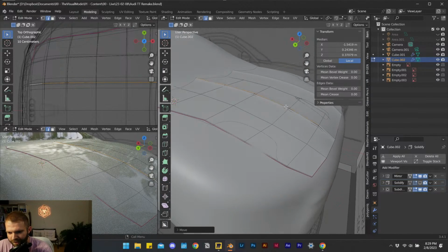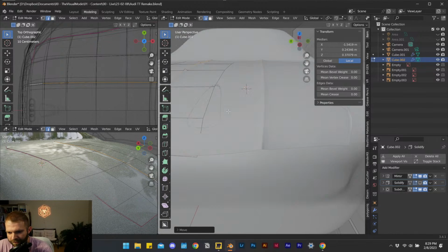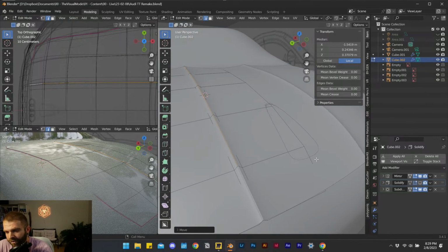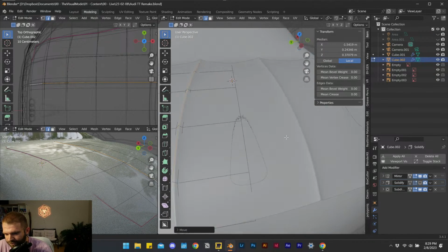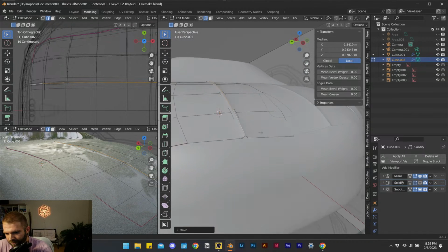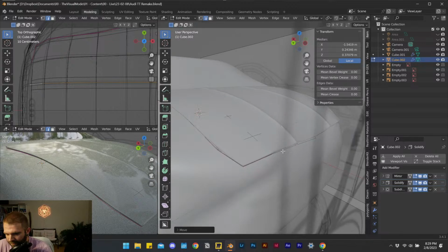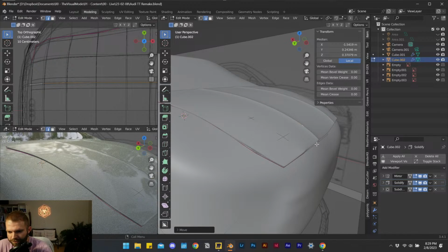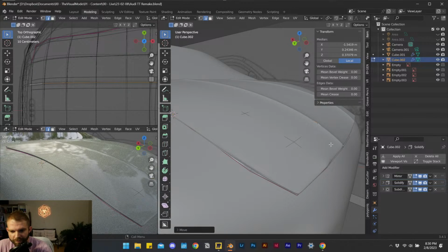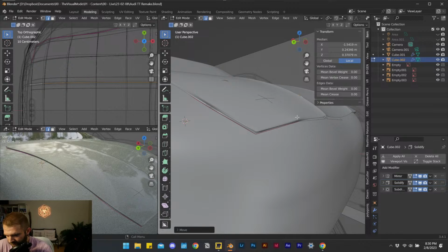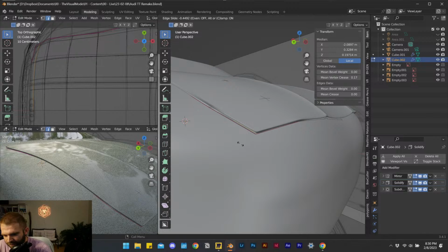And we see since we have our modifier, the mirror modifier, we're getting it over on the other side as well. So we'll turn on solidify, and see how our job here is looking. So not bad at all. What I am noticing is there's some weirdness happening at this edge, so it'd probably be worth adding a loop cut that meets the front fairly closely as well, but not all the way, maybe around,